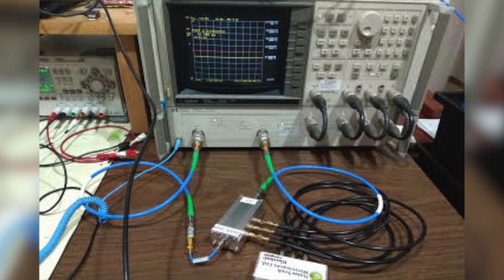Step 1 involves measuring everything in the noise path. So the noise path is defined by anything between the noise source and the device under test that you want to measure. Here there's a label on this port for the device under test, or DUT, and here is where the noise source will eventually be attached. So we need to characterize the circuit performance between those two.